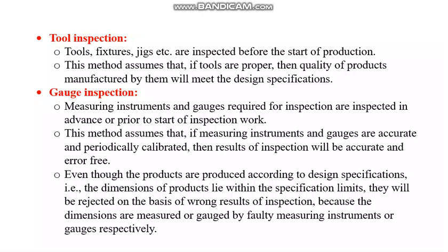You see, if you are having a UTM machine, a universal testing machine, and you are using it for many years, but if you don't calibrate it in the middle, the stress value that it is giving for our yield point, or for our ultimate point, or for breaking point, how will we know that that is the right value it is giving? There may be errors creeping in over a period of time, so therefore you have to do calibration.